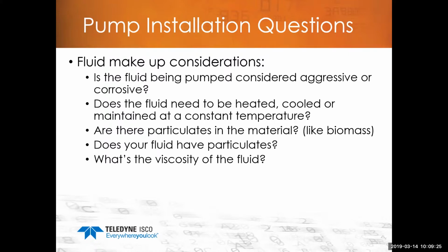And then obviously we talked about viscosity, right? So viscosity is a big deal. Molasses is pretty hard to pump because it's very thick. So is tar and things of that sort. But if you heat those up to a certain temperature, they become less viscous and easier to move through a system. So you want to look at the application you're trying to design, or what you're trying to do with the material that you're pumping, so you can keep it in the state that you want it in, along with helping it flow through the system properly and quickly at the flow rates you designed it to.